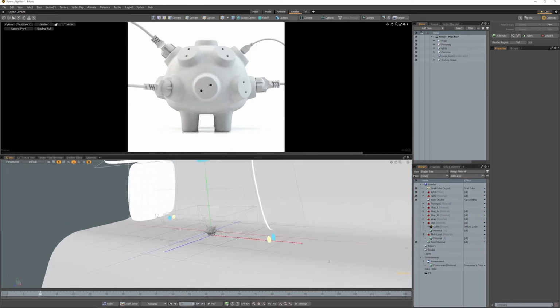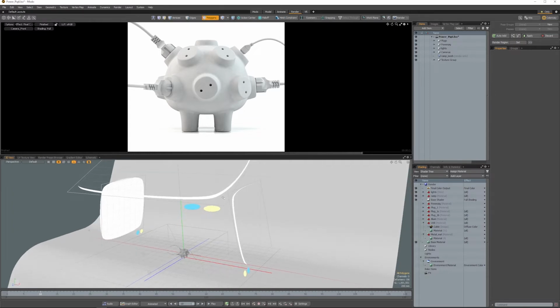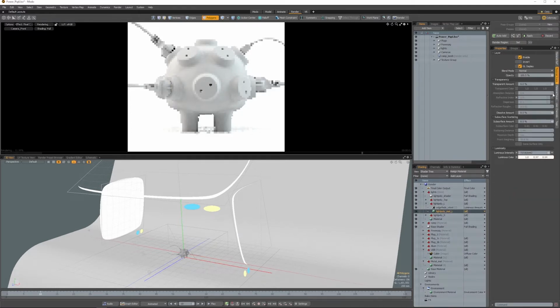So how was this light made? So this is made of 3 emissive planes, and they are here. So if you come here to lights and, for example, the left, select the material, you see luminous intensity, so you control it here. You could also click here on the handles, but the blue one allows you to change the color of the light. The yellow one should allow you to change the intensity. Something must be failing. This is quite an old preset that ships with Modo, so it doesn't seem to be working here. I would have to look, but you can still control it just fine.